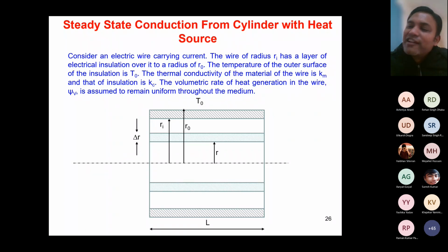I am not saying that heat flux will not be the same. I am saying, remember, whenever there is a change in the heat transfer area, heat flux is not the same. What is the same is capital Q, provided that there is no generation term. But at this interface, we can still equate the capital Q from this metal wire to the Q passing through this insulation because there is no generation term in the insulation. So at the interface. Yes, sir.